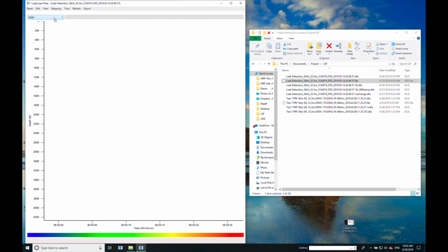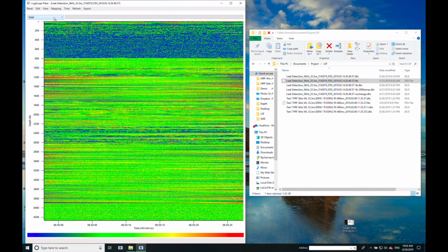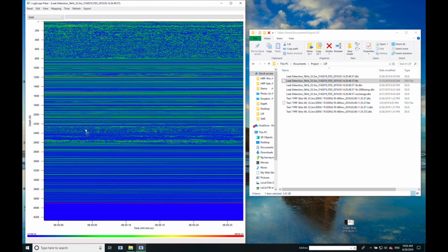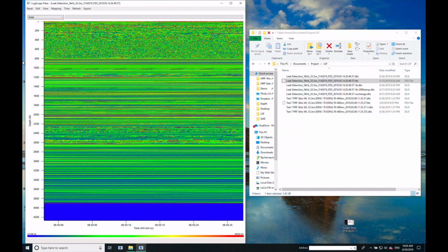We use the bar to go to the raw and it displays it normalized by trace. We can play with the normalization by going to view and switching off the trace normalization, and then we can manipulate the normalization by going to the bar down the bottom, and we can change it to be a fixed scale range that we set up. If we go back to view normalized by trace, we can then switch it back to normalized by trace.